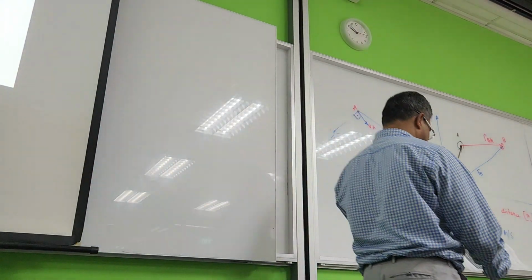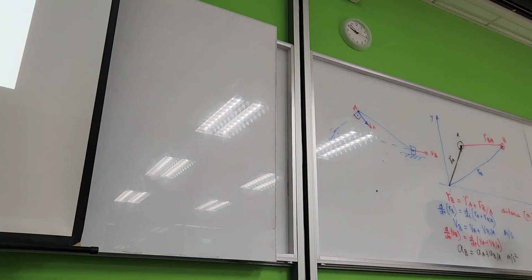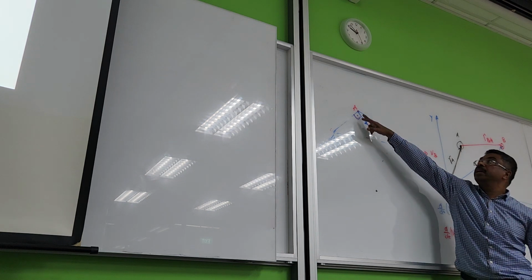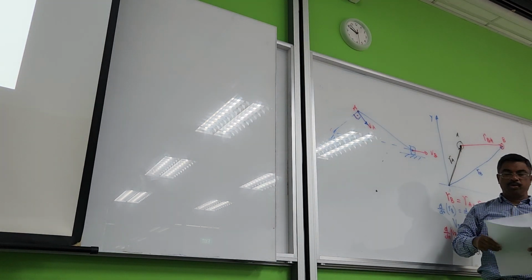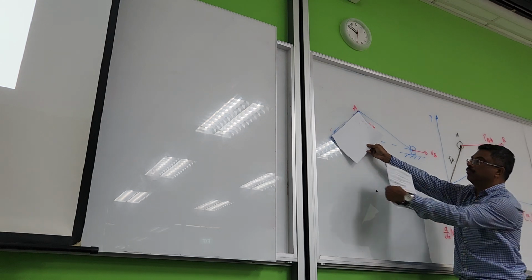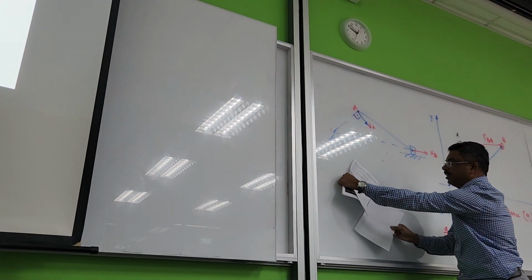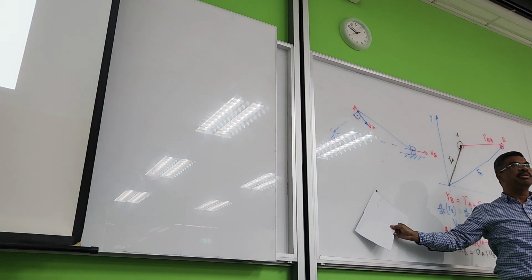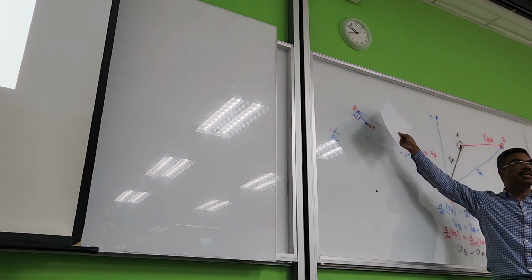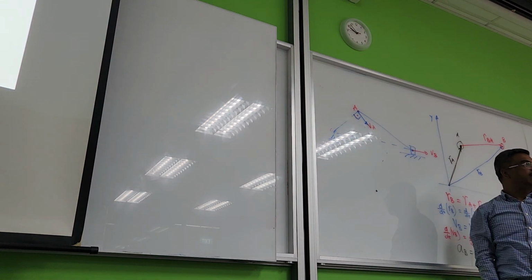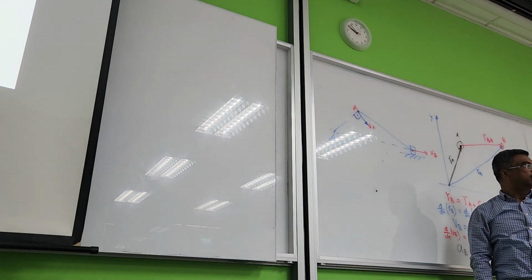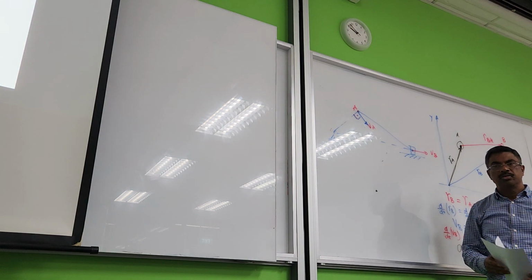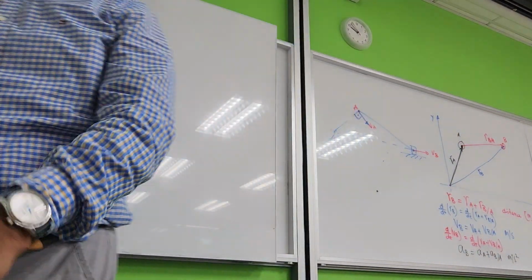So look at here how I do it. This is my, say, 90-degree angle. I draw these things to scale. That's the thing you need to make sure of. So now what I do, my objective is to bring that one parallel here, right? So I put it here, look at here. I put this one here, and then I put this one here, and then I put it here. You see? How many minutes does it require? Very little, a few seconds. But if you try to plot the 90-degree angle and all of these things using your compass, it will take about 10 to 15 minutes. And I do it within a few seconds. So that's how we'll be doing it.